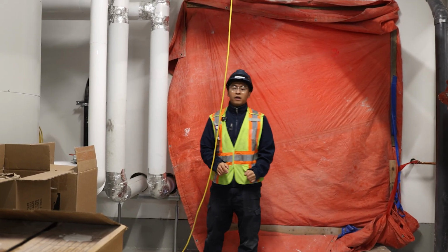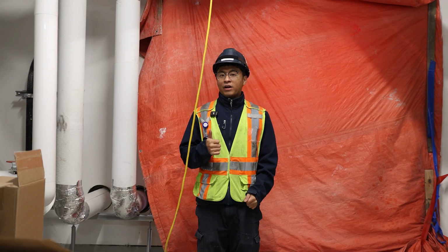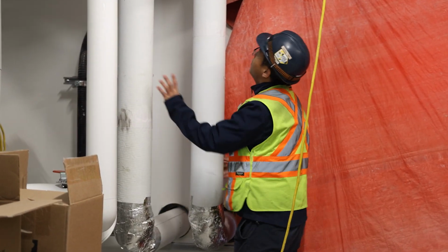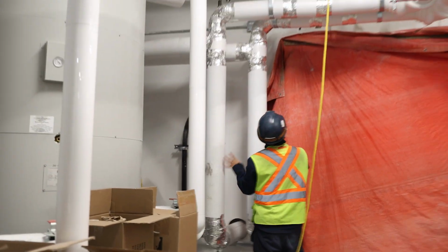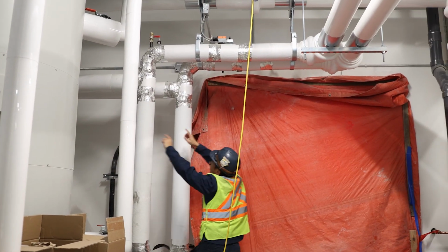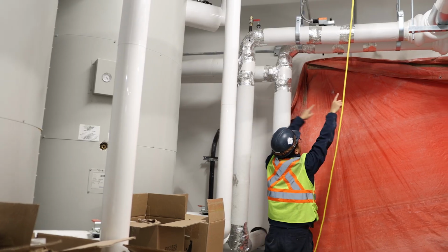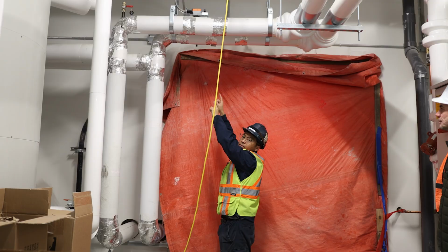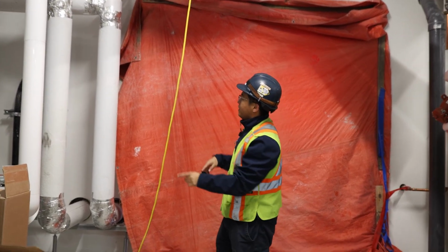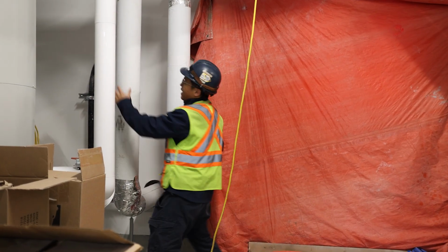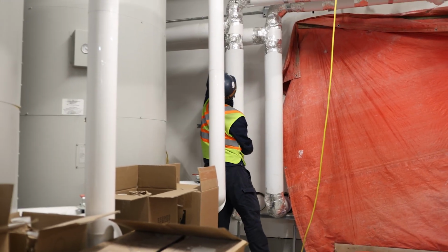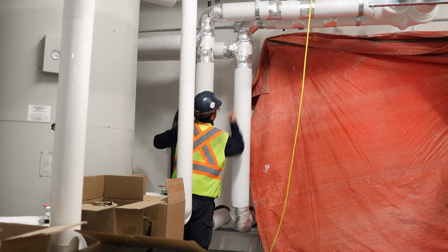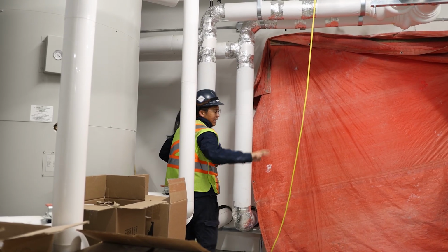For the HRV, as we mentioned earlier, there's only one coil that does the heating and the cooling. This will be the loop for the coil. This loop can be fed from here, or it can be fed from here. This is our cooling loop. Right now, the isolation valves of the cooling loop are closed because it's winter and it's doing the heating. So the flow is fed by the loop from the heating side. Flow goes this way, goes out and comes back. It doesn't go to the cooling side.